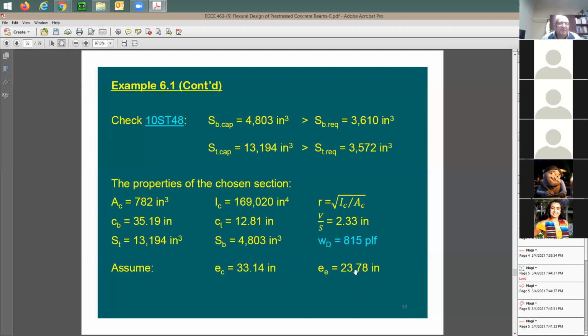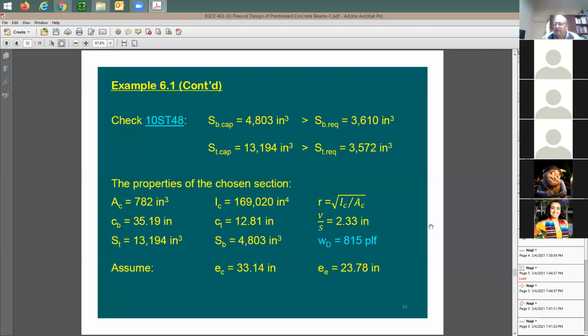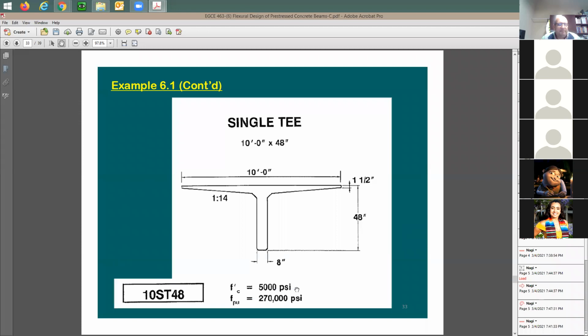So all of these values are recommended for you. Why do we recommend them? Because it's our industry standard. We have certain forms and certain equipment ready and certain setup, so we'd like you to use these values if you can. This is why you're not going to come up with your specialty and build it from scratch. No, you'd like to go to a precaster and just buy this item. So you're just taking these values from his catalog, and the catalog is this PCI manual, and this PCI manual has all the standard sizes.